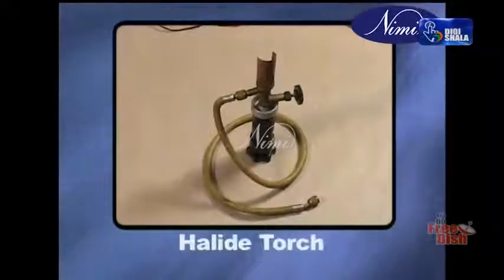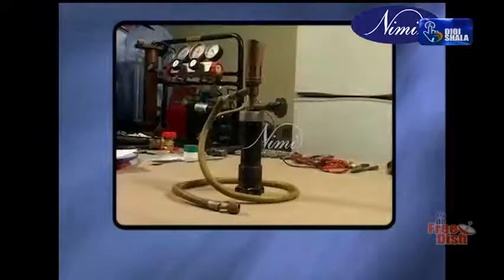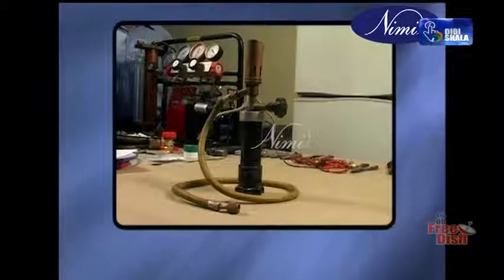Halide torch. A thin carbon element is heated by hydrocarbon flame in the halide torch. The rubber tube in the torch extracts air on the element when the flame burns. To find a leak, this tube is slowly moved on the outside joints of the system and fittings, and any slightest change in color of the flame shows the leakage.